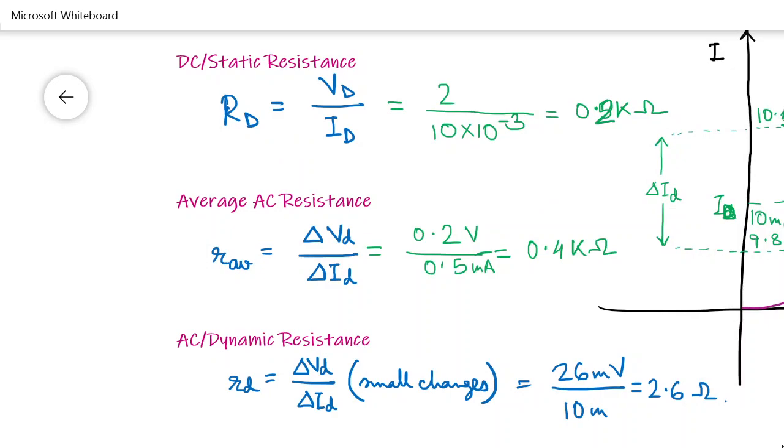Sir, what is the difference between Id and Is? Id is the current through the diode. Is is the reverse saturation current. Now Id is always changing. As you keep on changing the bias across the diode, the current through the diode will also change. It has a relationship with Vd, the bias voltage. But the reverse saturation current is specific to a particular diode.